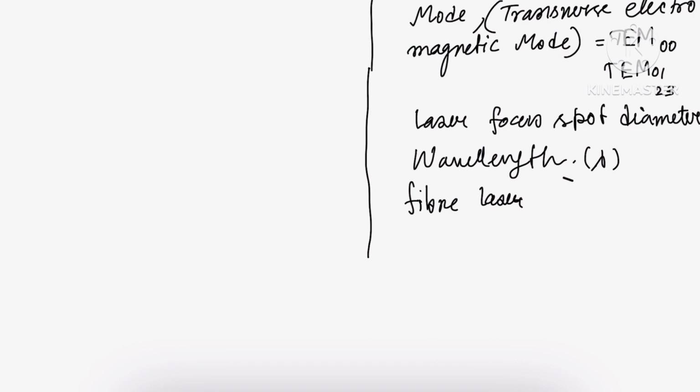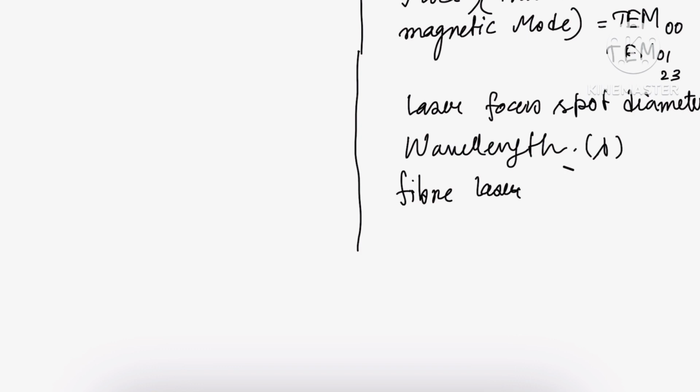But these are some types of laser. Depending upon the material being printed, depending upon the absorptivity of the material, we use different types of laser. Here let's focus on the fiber laser system. For LPBF, we are using a fiber laser which will be focused over the build plate. So this is the focus spot, and the diameter of this focus spot is typically 100 to 120 micron, as I also mentioned in my last video. This 100 micron focus spot will result in the micron level accuracy in the printed part in LPBF.